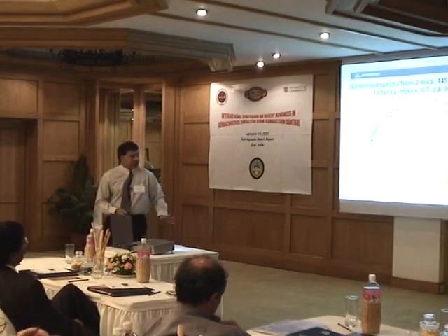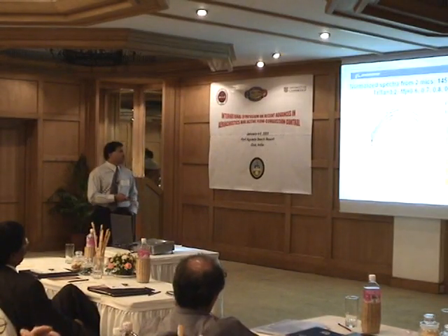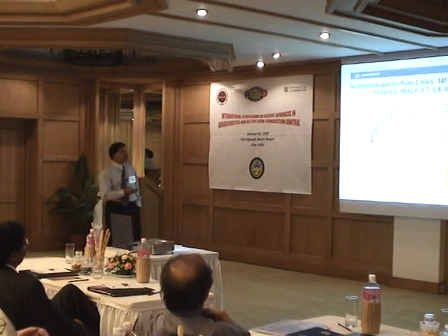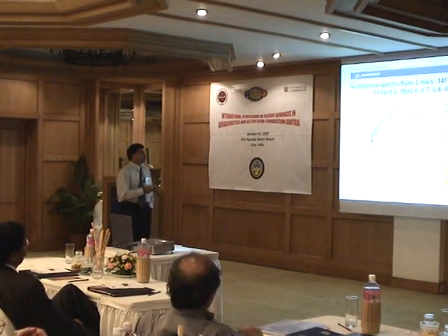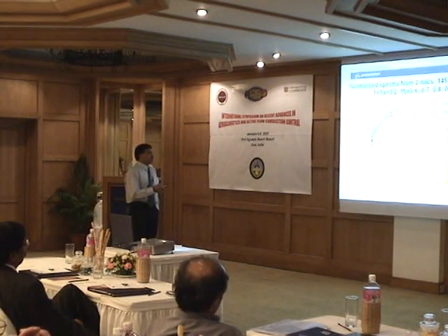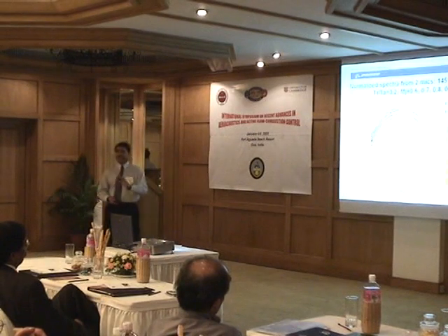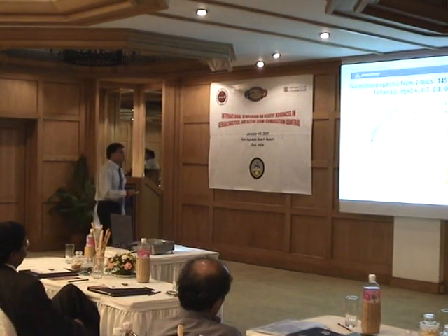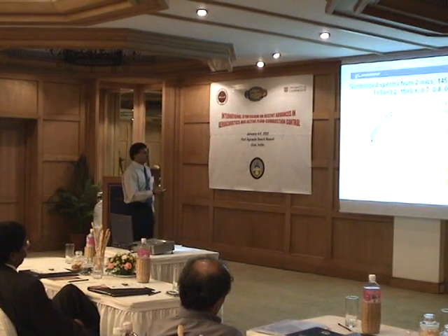So what I'm going to show next is the progressive increase in the convective Mach number. We have the jet heated at a very high temperature ratio of 3.2, and you increase the Mach number from 0.6, 0.7, 0.8, 0.9 to 1. And this is at an angle of 145 degrees, which moves the microphone away from the collector. There's no reflections from the collector. The black one is the closest microphone, which is at a distance of 16 feet, and the red one is at a distance of 26 feet.